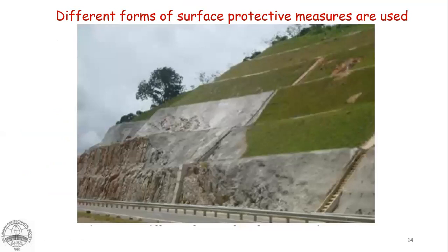Along with the surface drainage, surface erosion protection measures are to be taken. Now, in this particular site, you can see there are berm drains like that, and then the berm drains are sloped into the cascade drain. So there are cascade drains bringing it down. Now, this is an area where the exposed material is soil, residual soil. So in that, vegetation had been introduced.